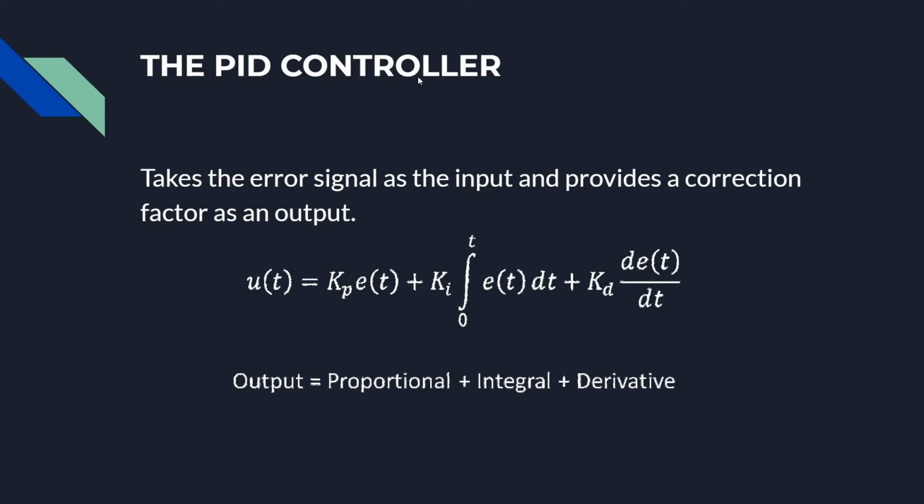So controllers don't necessarily have to have all the proportional, integral, and differential components. It could be a proportional controller which would just have P, just integral, just differential, or PI, PD, etc. But in most cases, you'll find either a proportional controller, a PI controller, or a PD controller. You don't generally have just integral, just differential, or integral differential controllers as such. For most robotic applications that I'm talking about, you would use PID or PI controllers.